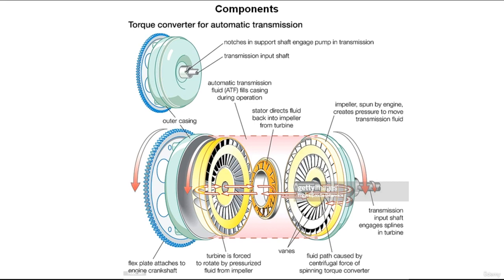At the rear of many torque converter shells is a hollow hub with notches or flats at one end, ground 180 degrees apart. This hub is called the pump drive hub. The notches or flats drive the transmission pump assembly. At the front of the transmission within the pump housing is a pump bushing that supports the pump drive hub and provides rear support for the torque converter assembly. Some other transaxles have a separate shaft to drive the pump.